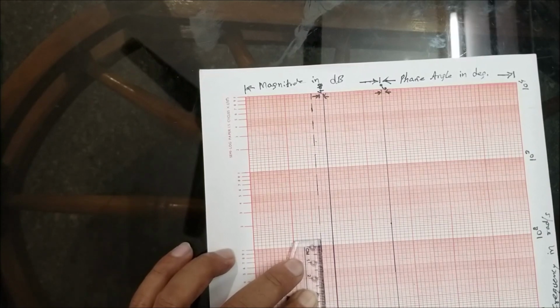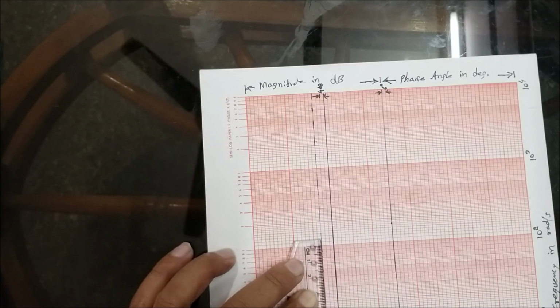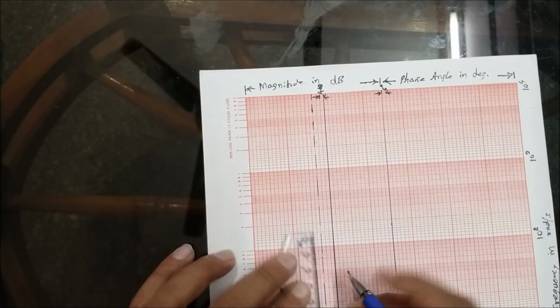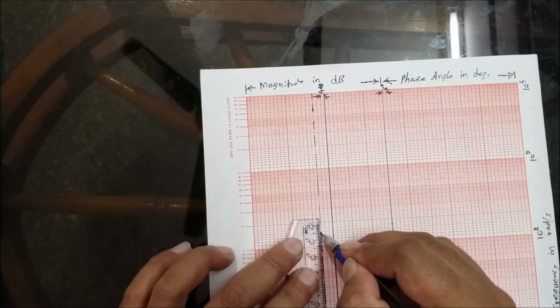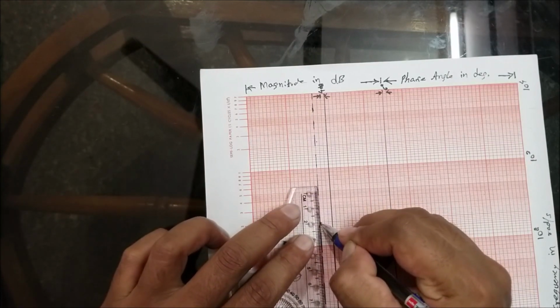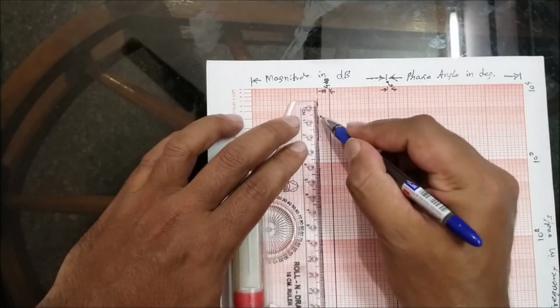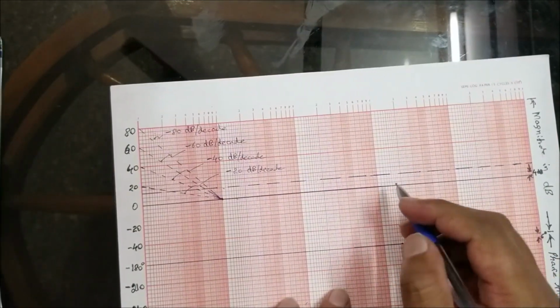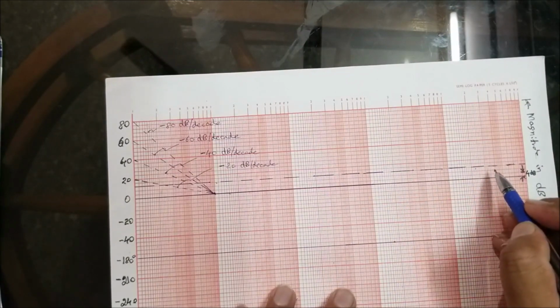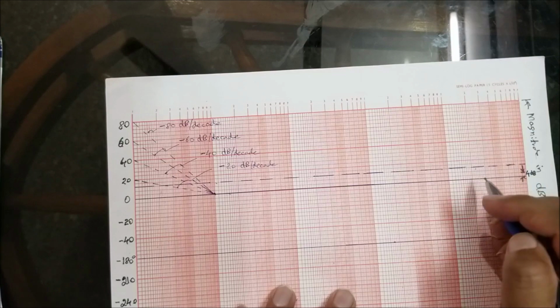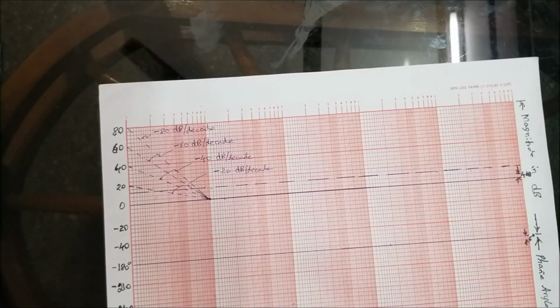If we don't know the value of k, then the shift will not come into the picture. The problems which involve calculation of k do not contain this shift, because we should calculate how much shift is required for the given gain crossover frequency, equate 20 log 10 k to the gain margin, and then find the value of k. That is for problems which involve calculation of k. But for this problem the value of k has been given. For the shift of 12 decibels, I am determining whether the system is stable or unstable. Since we have the shift, the very first line I have is minus 40. You can see here.